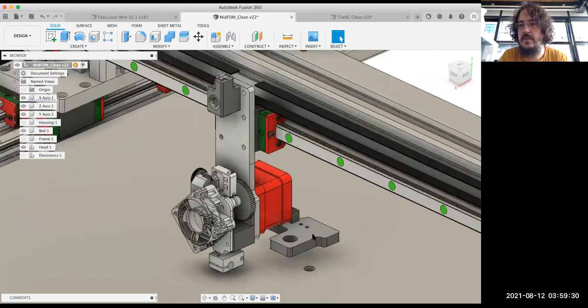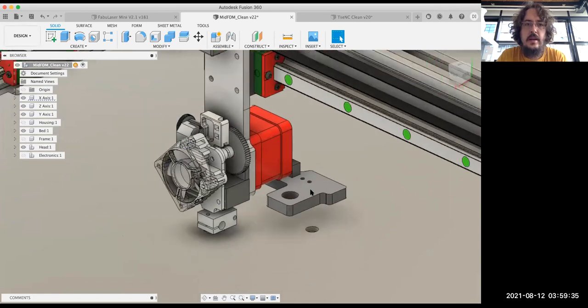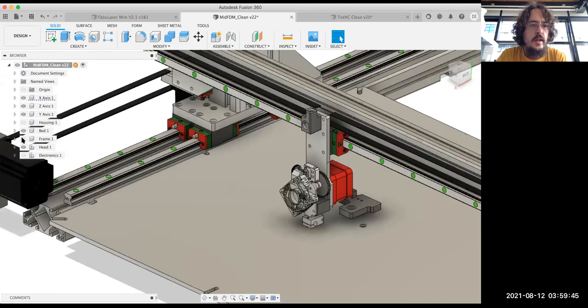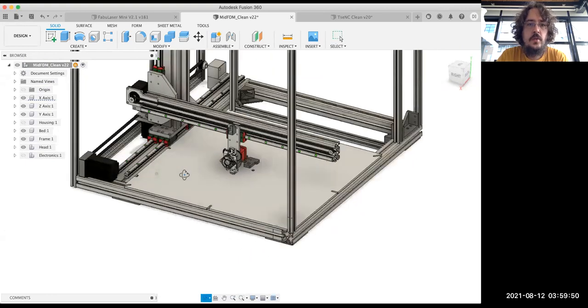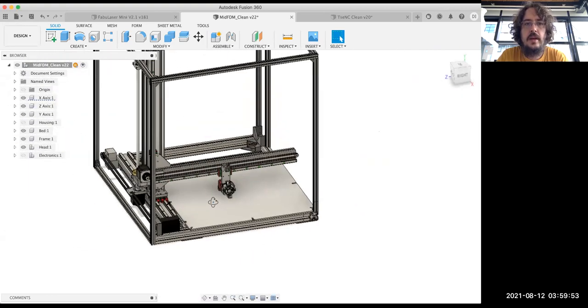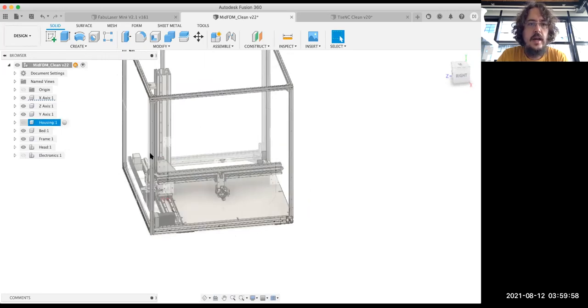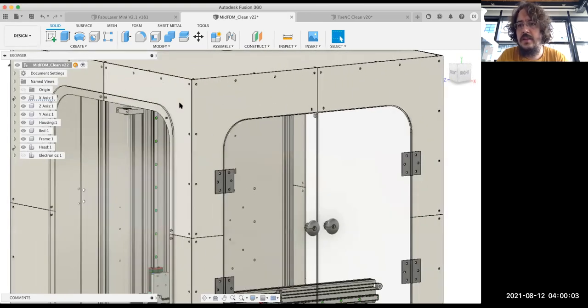So for the bed leveling sensors, we use inductive probe sensors to level the bed, and also for the z-axis Z-min end stop sensor, and then we use normal mechanical micro switches for the rest of the machine. So the overall frame of the machine has been built on this structure, and it's made by very cheap 2020 aluminum profiles, just to make a housing for the machine. So the machine is fully enclosed, and the housing is realized by using aluminum composite panels that are very easy to cut, and also laser cutting and acrylic.